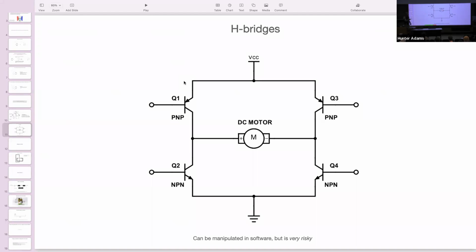So what we're doing in this class and in your program is one of the two: your two PWM outputs are each controlling one of the pairs together. Say you want the motor to turn in this direction at some speed. You would do that by making the duty cycle to the PWM channel that controls these two transistors 0, just to say you turn those off.